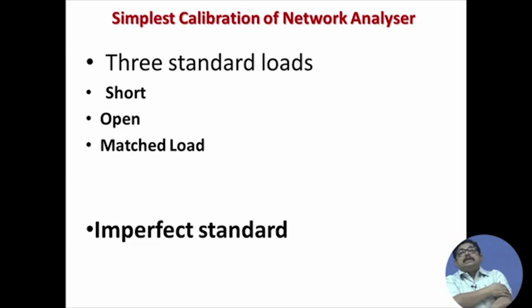But getting the standard loads is a problem. I can design a short, I can say that reflection coefficient is -1, but in reality, if you want to fabricate a short, it is a metal plate. Now, that has a thickness. Whatever you do, it should not absorb anything, but generally some waves go inside.